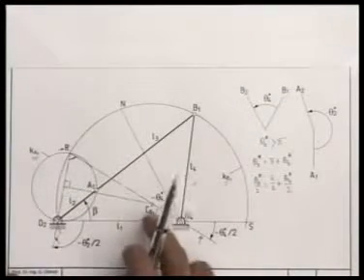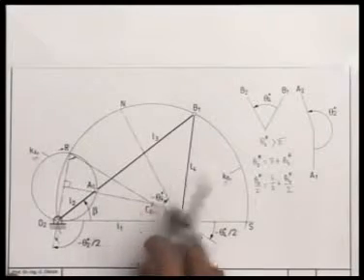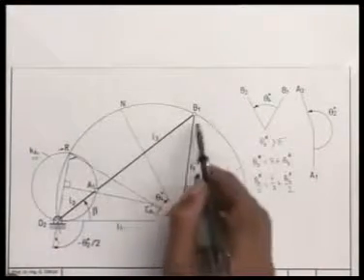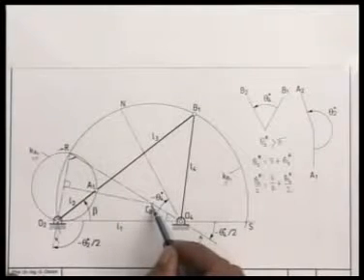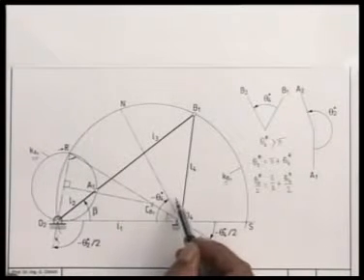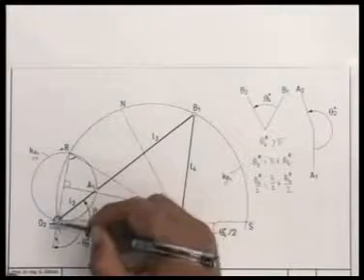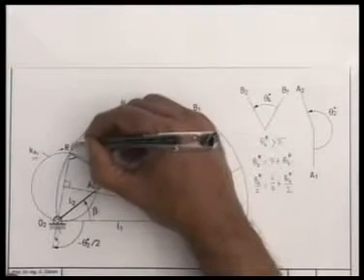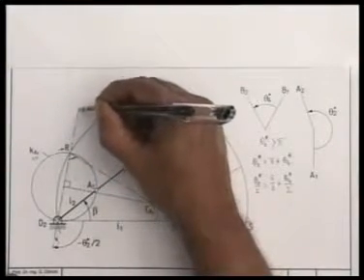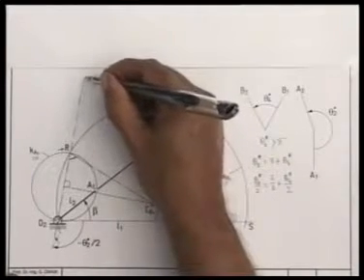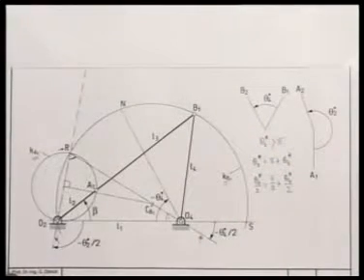They will never meet. Consequently, the center CB1 goes to infinity, and this KB1 with CB1 as center degenerates into a straight line passing through O2 and R. That means KB1 will be the straight line which is nothing but the extension of O2R.